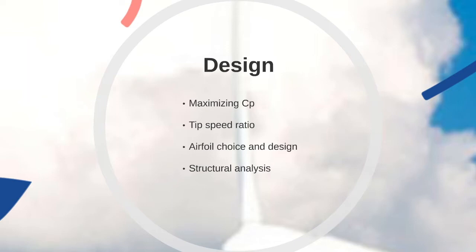We began our experiment by choosing our tip speed ratio, which is the ratio of the blade tip velocity to the incoming wind velocity. If the TSR is too low, the wind turbine would tend to slow and/or stall. With a higher TSR, the turbine would spin very fast through turbulent air. Power would therefore not be optimally extracted from the wind. Moreover, it would be highly stressed, at the risk of structural failure. Using empirical data, we finally settled for a TSR of 4.5.